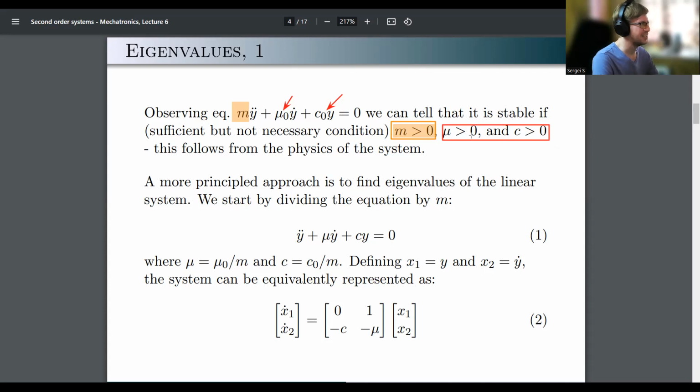I think basic sanity will tell you, okay, now I have to compute eigenvalues. So while I like this test, I definitely don't see someone using it to prove instability of the system and just walking away. In a practical situation, a situation which you care about, if this test fails, you would compute eigenvalues and do a proper test. But usually it is just meant to calm yourself down when you see the second order system, to just make sure, okay, it's supposed to be stable, it is stable.